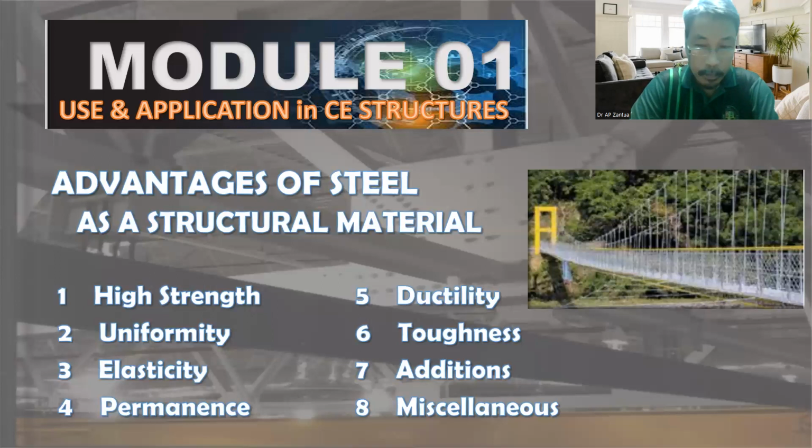Usually these metal or steel components are joined or connected by welding, bolts, or rivets, so some parts could easily be replaced. For example, on one span, you can just replace a small portion by using plates and bolting or riveting them on that particular area.